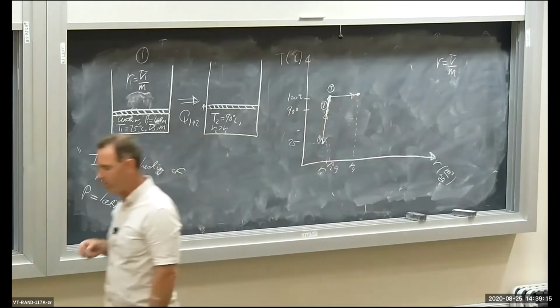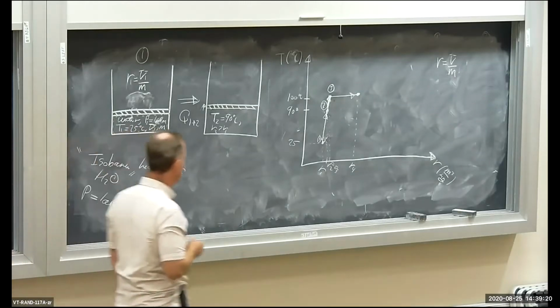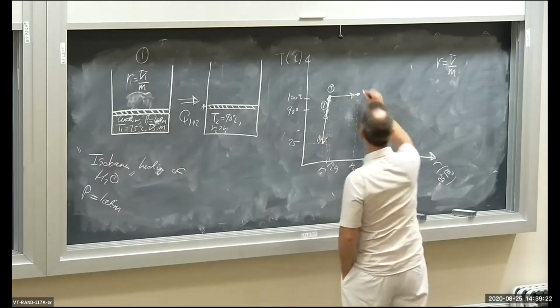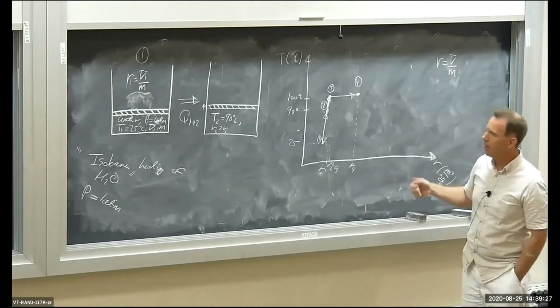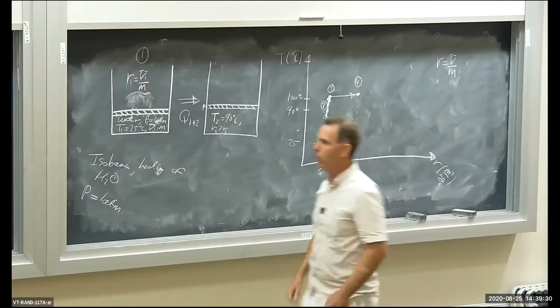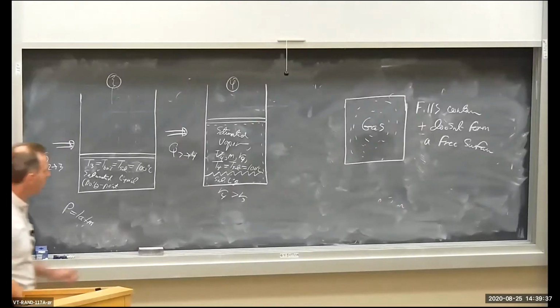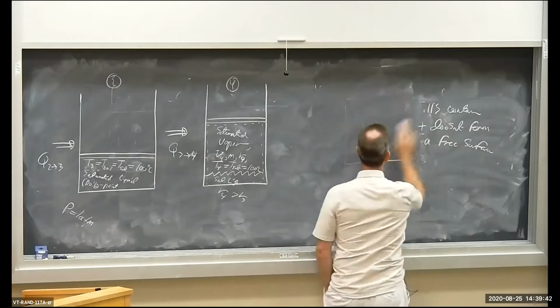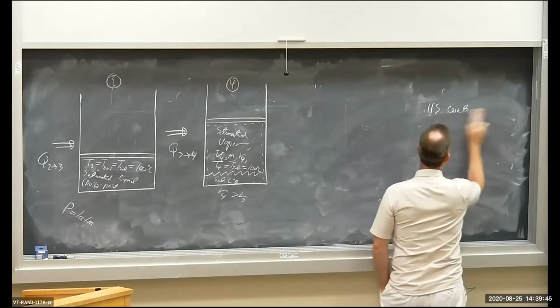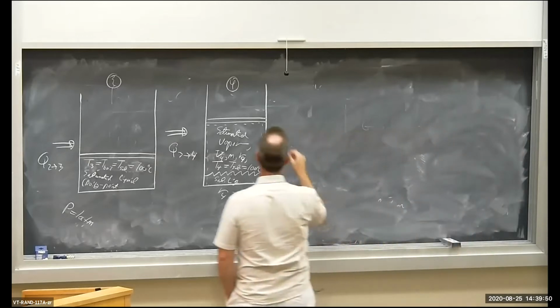So during a boiling process, provided pressure is constant, temperature is constant. So state 4 has the same temperature as state 3, and its specific volume has gone up because the liquid is boiled away and volume has increased. So specific volume has increased as well. Let's add some more heat. Let's get to state 5. Let's add just enough heat so that all the liquid is boiled away. Just enough heat to boil away the remaining saturated liquid.